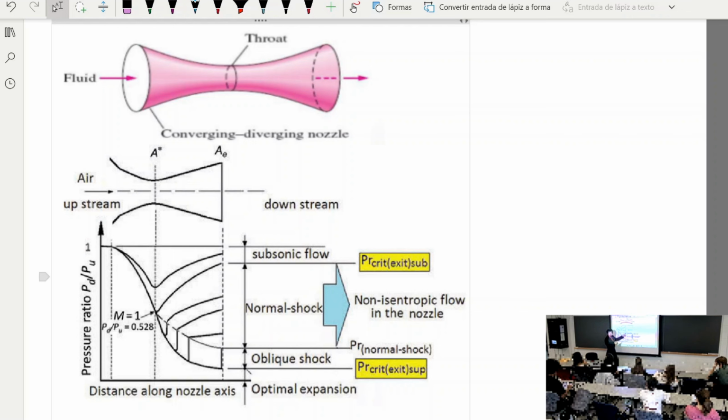From the Mach number, you know the density, because usually you are given the upstream conditions, the atmosphere condition upstream. You know the stagnation density and the Mach number, so you know the actual static density. Knowing density and pressure means you know the speed of sound, and with the Mach number, you know the velocity. Knowing velocity and density, you know the mass flow here, and therefore the mass flow through the entire nozzle, because it's a steady state.